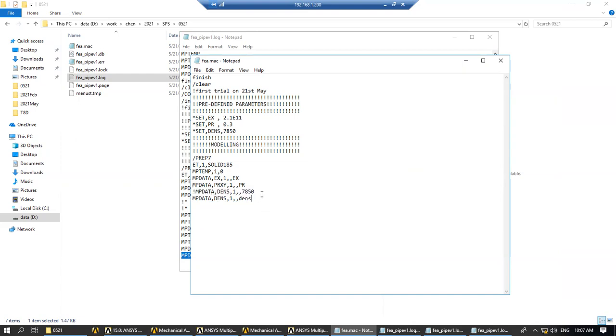Sometimes you have more than one option, so you can type them both there, deactivate one and try to activate the other one. Or alternatively, I can use the first one and deactivate the second one. This way is better than deleting one and trying the other, and then if the other one doesn't work well, you have to go back to the first one that you deleted. So it's better to have many there and just use this exclamation mark to deactivate one of them.